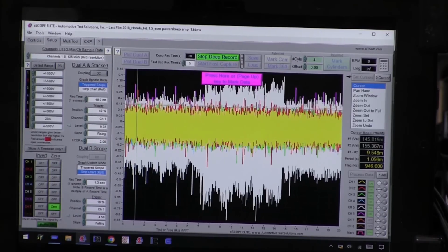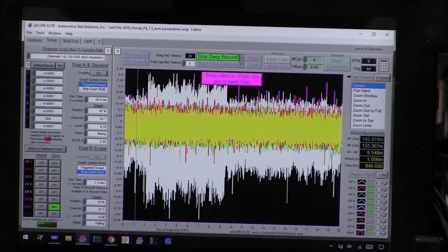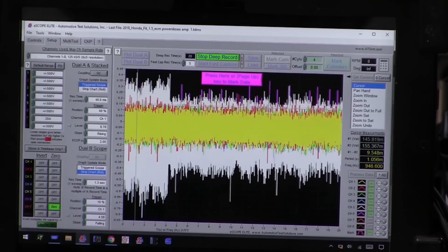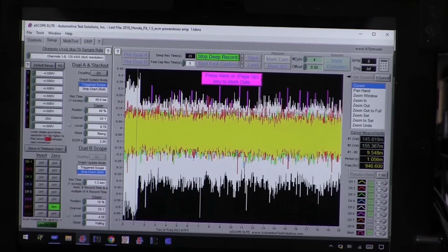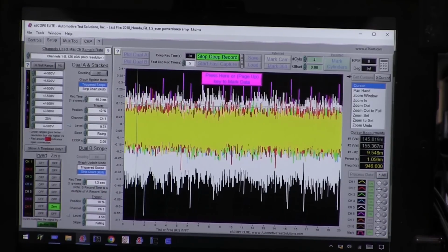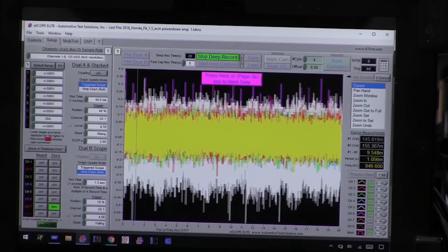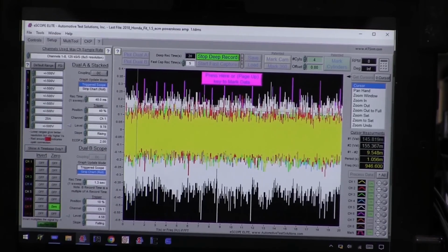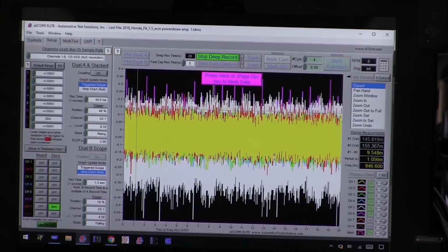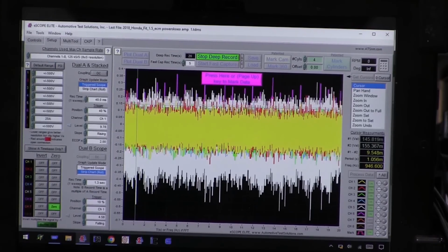Now guys, all of these motors on these throttles have some noise. Whenever you're looking at throttle circuits, you'll always see this noise because it's turning the motor on and off so rapidly, and that motor has a magnetic field that's falling, and they're turning it on and off fast enough that the magnetic field can't completely fall, so it can hold that throttle plate very stable. This is more normal. This isn't what I'm looking for. This isn't the problem, guys.